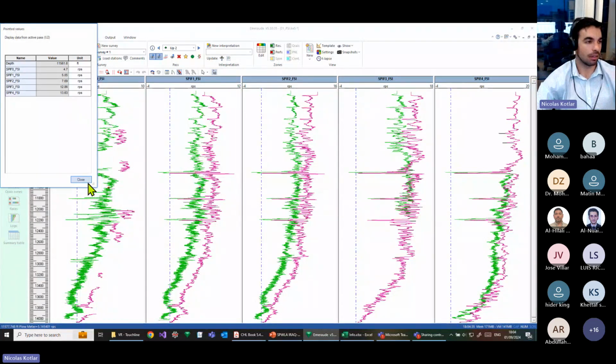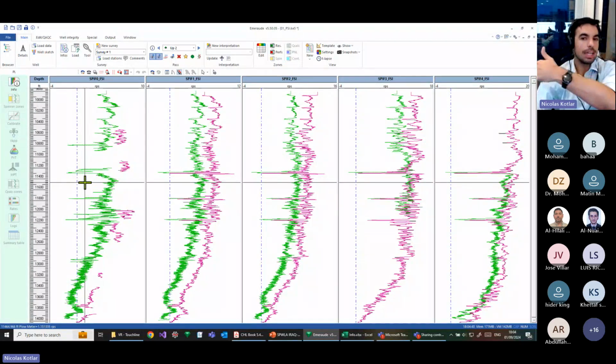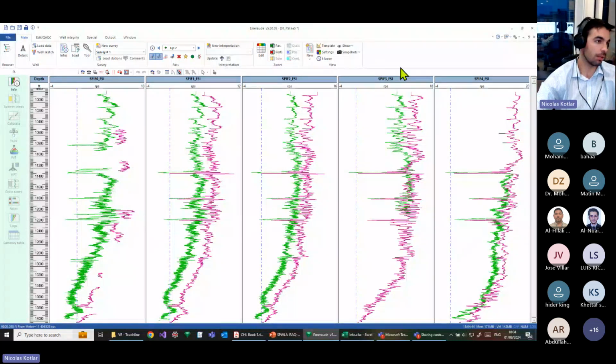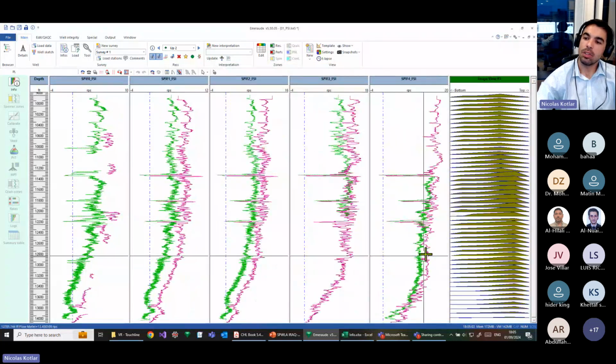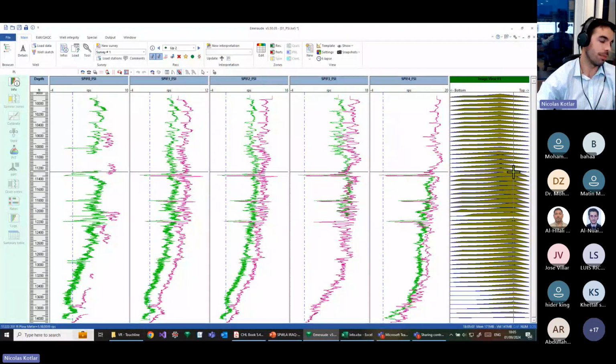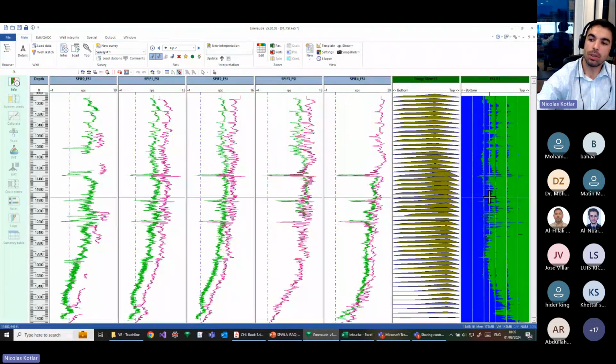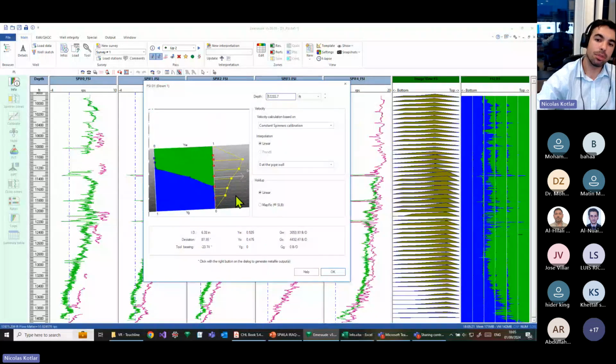So this is telling us that the lighter the fluid, going from the bottom where we have water to the high side where we have oil, fluid velocity increases, right? That's what we expect for stratified flow. There is another image that shows that. If you click image view and change this to velocities, let me increase the amplitude a bit, and increase the spacing as well. You can use an image like this that shows where the peak of the velocity distribution is, as seen by the spinners. By the way, something I didn't show is that when you look at the cross sections at a particular depth, apart from showing the holdup distribution, these yellow points are the velocities as seen by the spinner, right? You can see that on the low side of the cross section the velocities are lower, and on the high side they are faster. This is what we expect for stratified flow, right?